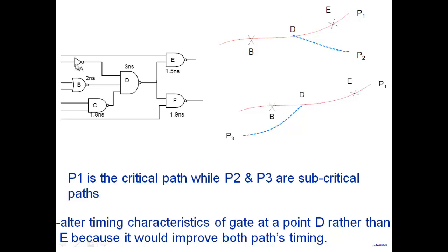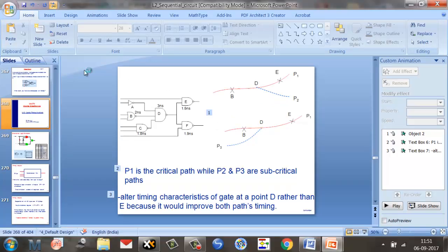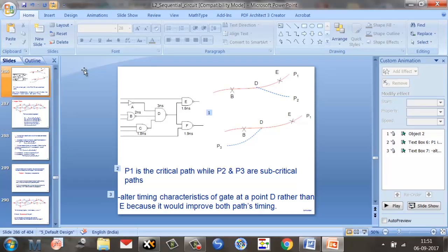So design never goes in a nice linear manner to the end. It will never go like that. It is highly iterative unless you're doing a very routine design, something you've done earlier. Then your experience comes into the picture. Otherwise, there'll be a lot of iterations. You'll have to go back and forth. Okay, so please remember, all these delay values are tentative. So it's very important that we go to the next stage. We start doing transistor level, start calculating delays and understand where these delays come from. Okay, all right.